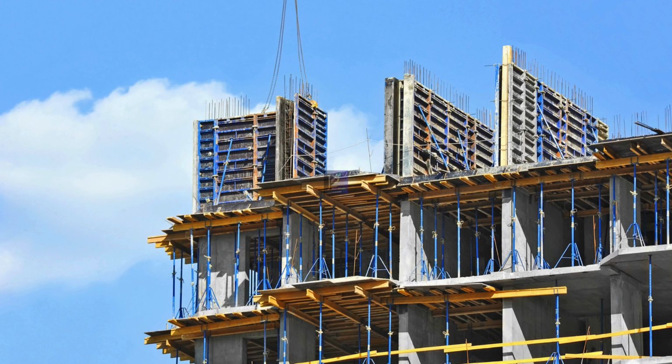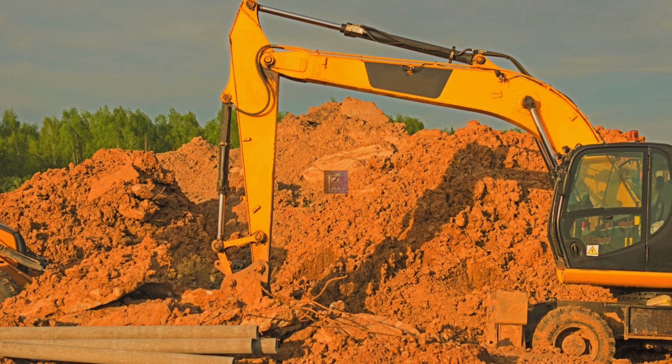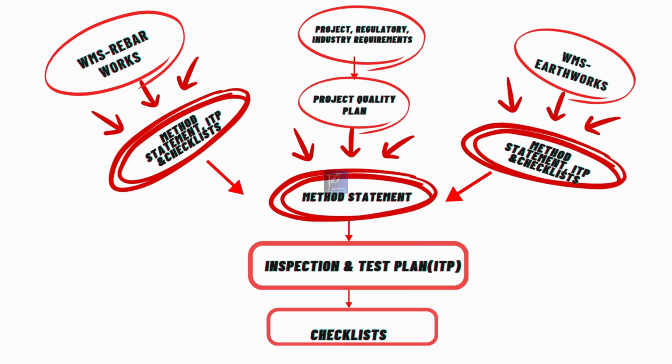It's important to note that reinforcement, formwork, earthwork, and all pre-concreting activities should have separate method statements. It's not advisable to combine all these into a single document. However, all relevant inspection test plans and checklists must be referenced within the method statement if they need to be used while doing the particular activity. I'll explain this in more detail when we discuss ITPs.